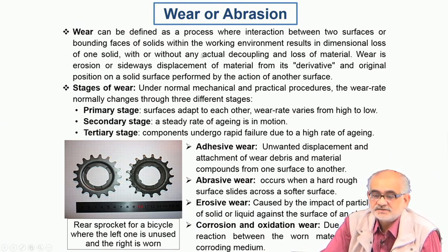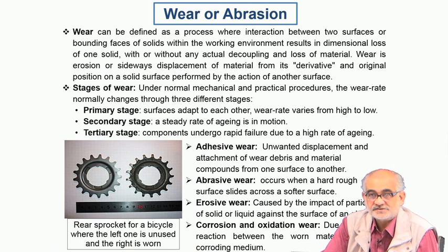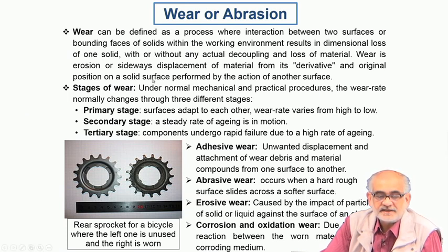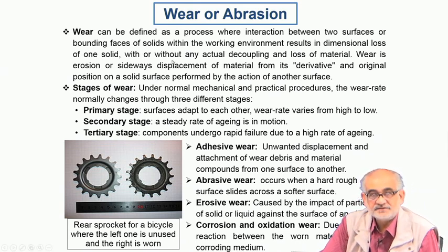Under such derived compressive loading, there could be momentary welding of two asperities, at least the tips of the asperities, and the subsequent fracture of such cold welded bonds. So in the process, a portion of the material will be dislodged, and that is the volume of the material which is lost in the process, called worn debris.